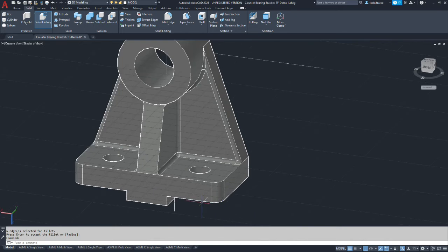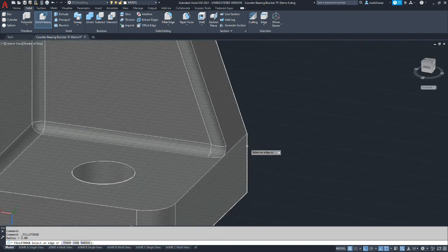So now we're on the last fillet and probably the most finicky. It's actually all rounds. And the first time I did this, I had to do it 3 times, but I realized that you need to include this segment here in the back. And if you miss any of the little selections, it won't work. So we're going to select fillet.